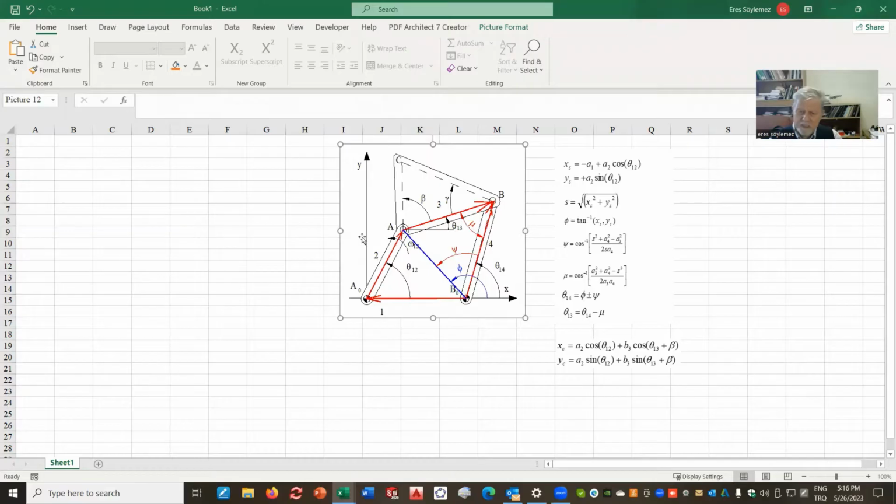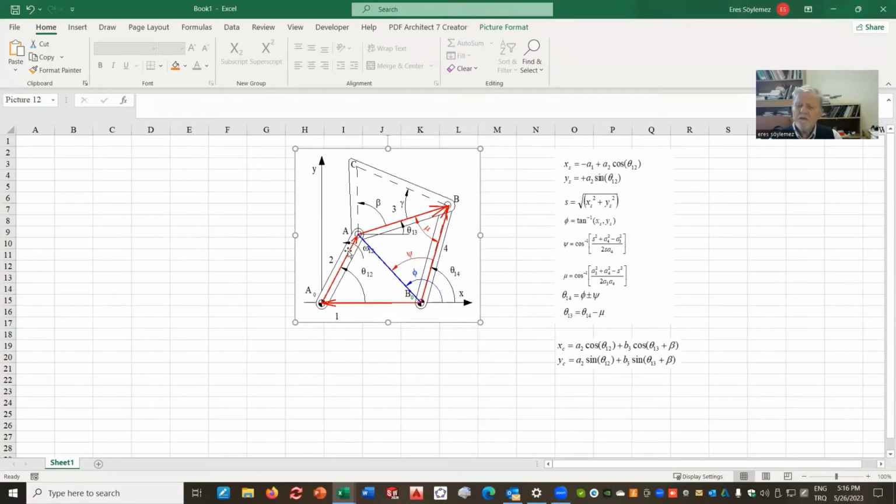When theta 1,2 is given, you see, first, we have a triangle. When you draw this diagonal, you don't have to draw it, but you have to imagine that there is a line drawn. We form a triangle. In this triangle, we know this side, the link lengths are given.